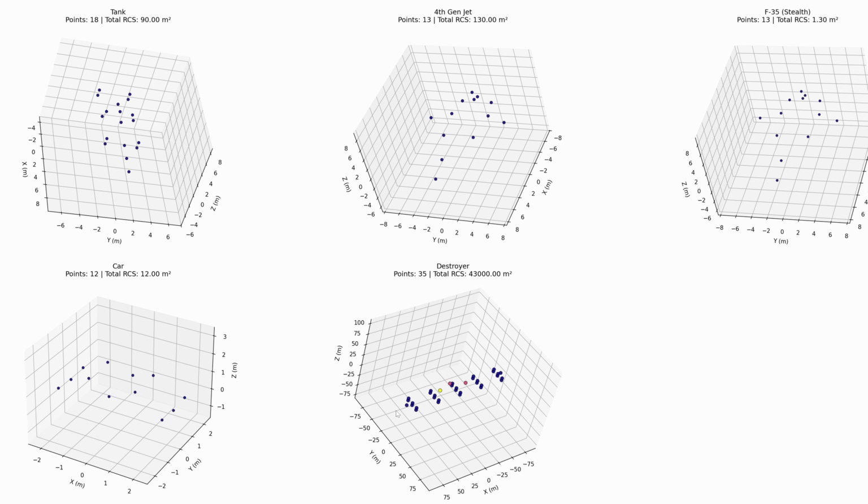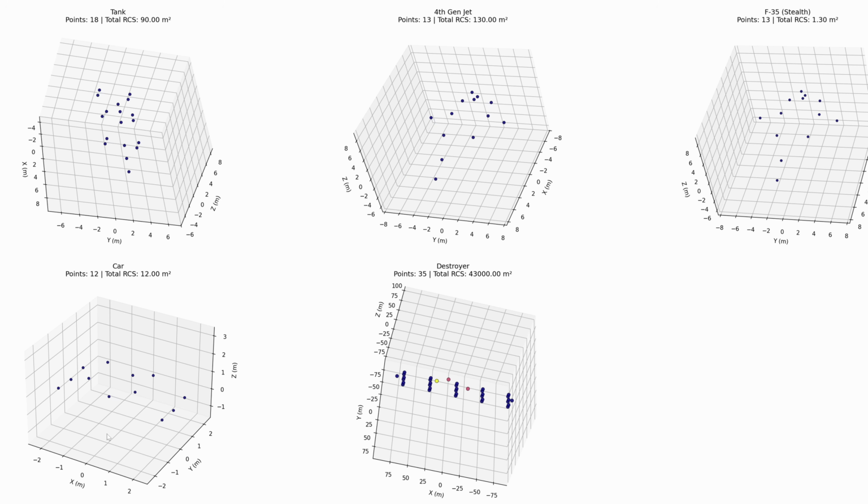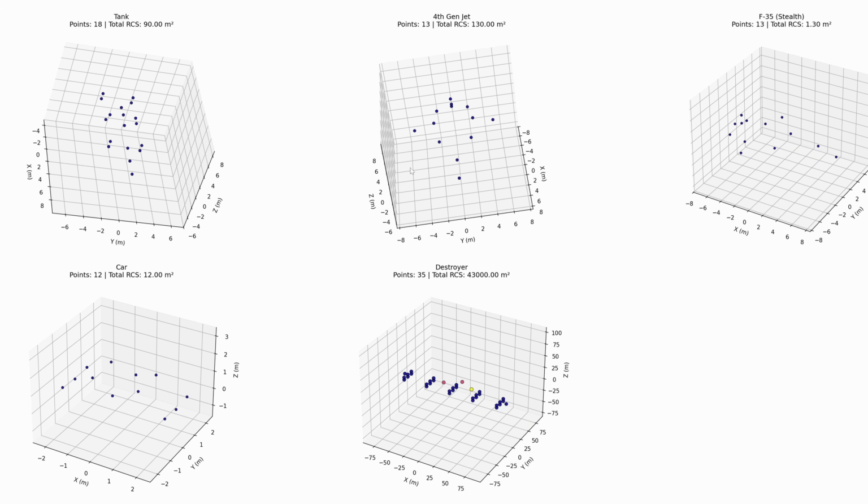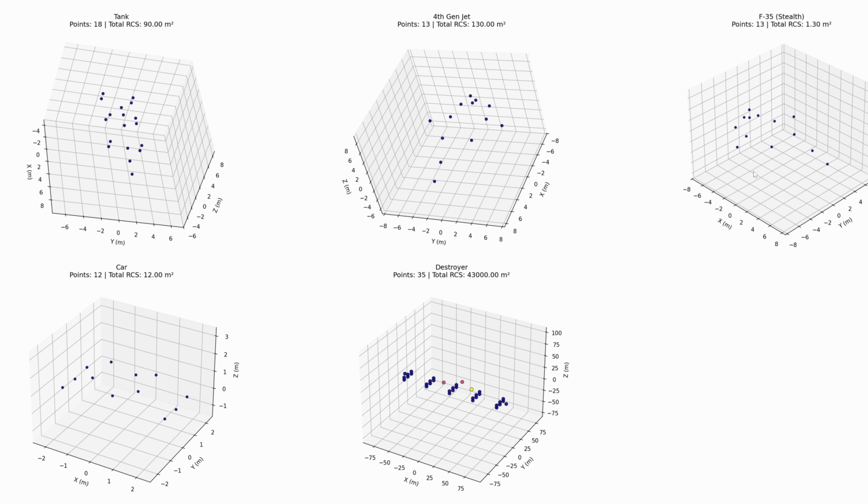We will be sticking to vehicle models made from point targets in the simulations. I tried to simulate a full 3D scene, but I found out the hard way that it is completely impossible to ray trace thousands of pulses like this on my consumer GPU. And this is why you won't find any code for complex 3D simulations of SAR on the internet. So just keep in mind that point targets are brighter than distributed targets, and they will not have shadows, and they will not have all of the same artifacts that you would see in a normal image.